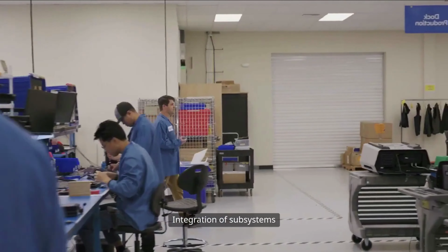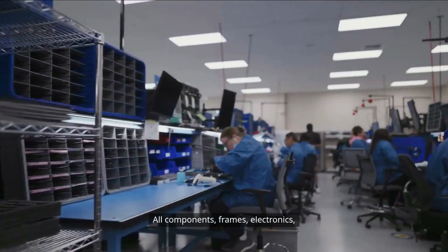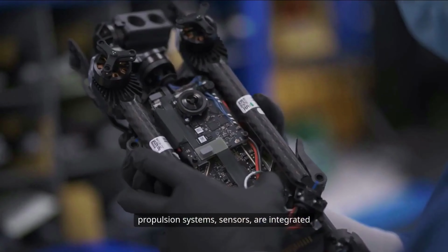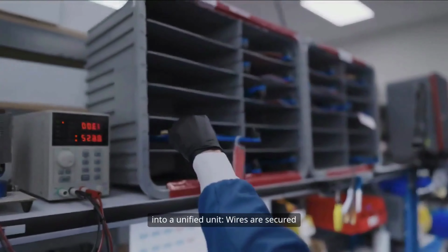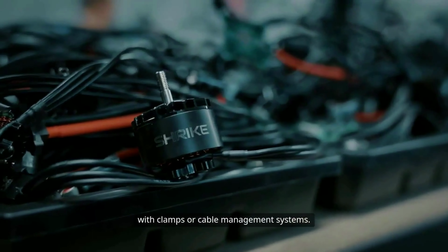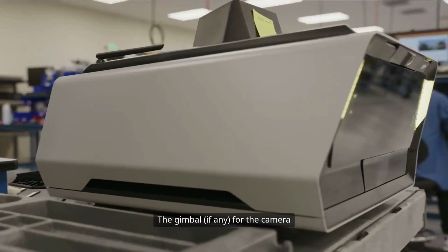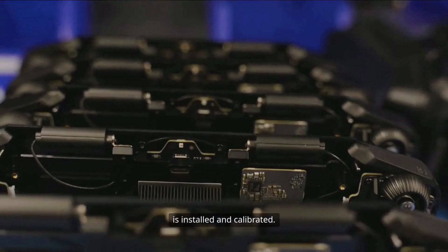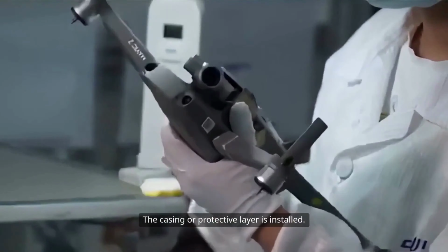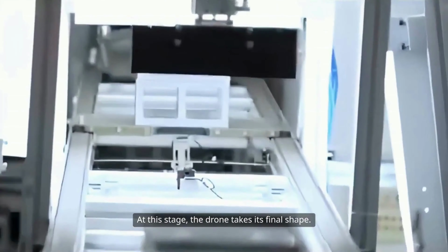9. Integration of subsystems and mechanical assembly. All components, frames, electronics, propulsion systems, and sensors are integrated into a unified unit. Wires are secured with clamps or cable management systems. Connectors are locked firmly in place. The gimbal, if any, for the camera is installed and calibrated. The landing gear is firmly attached. The casing or protective layer is installed. At this stage, the drone takes its final shape.